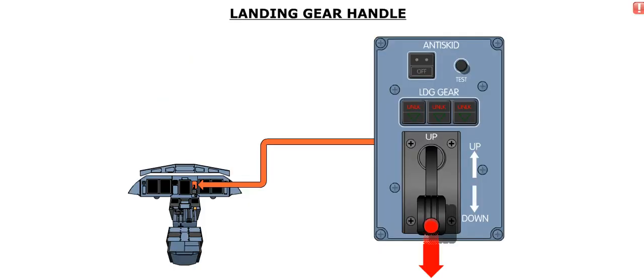The landing gear is extended or retracted normally by the landing gear control lever on the center portion of the flight instruments panel. The lever must be pulled out in order to raise it or lower it. If the lever is placed in the down position, a red light will illuminate in the lever, as long as the gear is not sensed to be in the down and locked position.